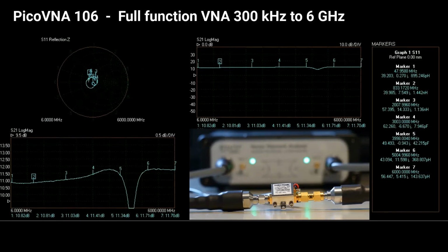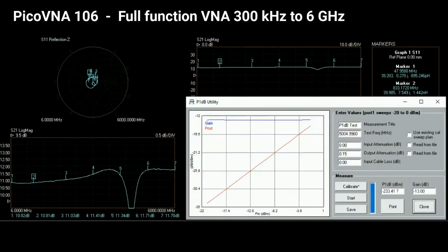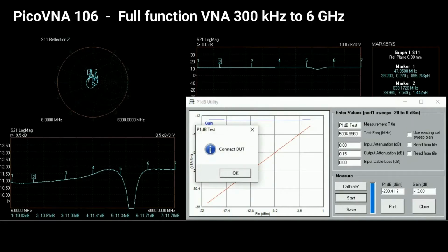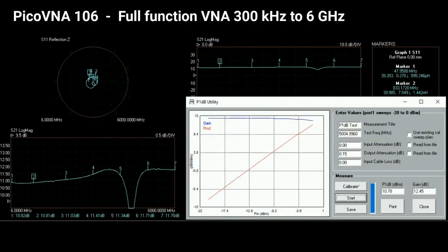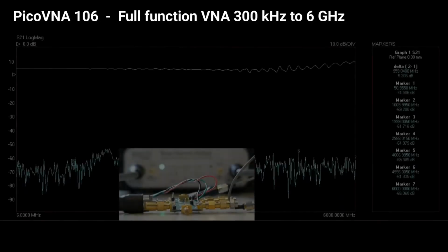Here, P1 dB compression of this amplifier is under test. This at a single frequency, swept frequency also supported. Similarly, phase mod due to AM is supported in a second utility, and a CW signal source utility adds yet more flexibility to the product.